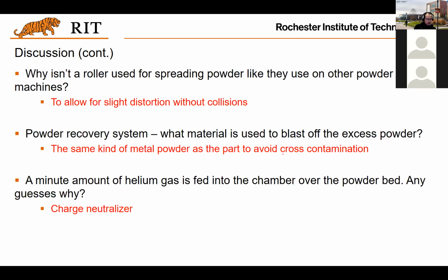Another thing is the excess powder reuse, right? How you reuse those powders, and how you remove the powder from the parts and reuse them. That requires a blasting process. In the blasting process, the same kind of metal powder is utilized to remove the excess powder on the printed part, and that is to avoid the cross contaminations.